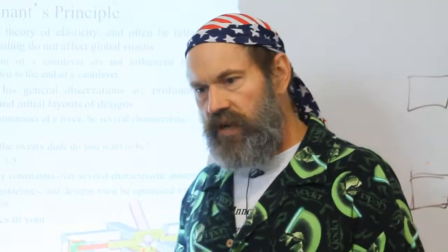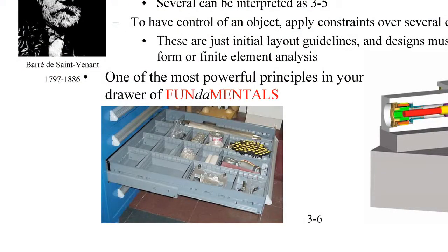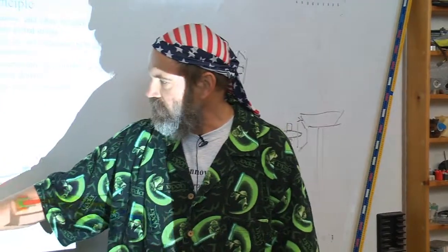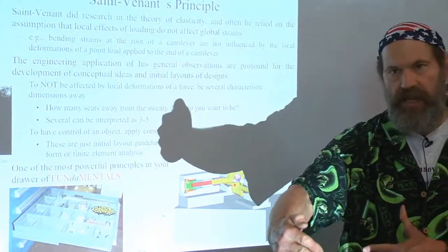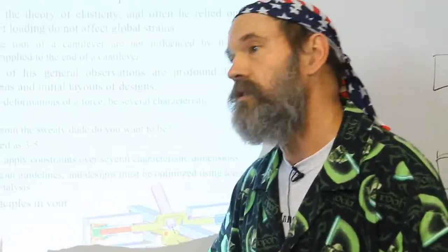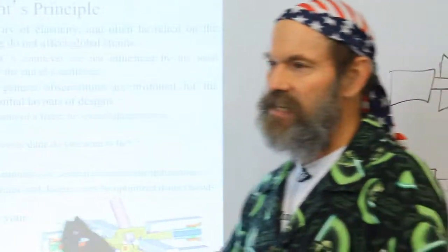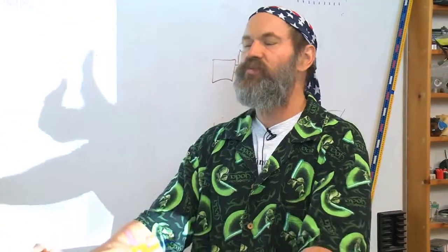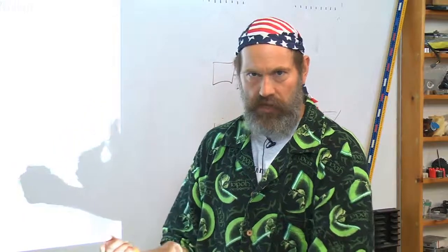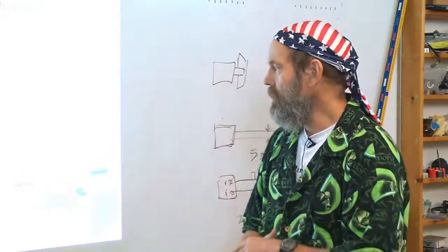And notice we have things like drawers. You ever have one of those old dressers that were made real cheap? And this is a really expensive drawer set here. It's got ball bearing slides on it. It's wide out, and it rolls nice. It's what's called a compound slide, notice. So you always have a long engagement length of bearings with respect to the width of the drawer, so it always slides nice and easy, as opposed to some of those dressers which have just wooden runners way on the outside of the drawer, and it jams and it fights you.